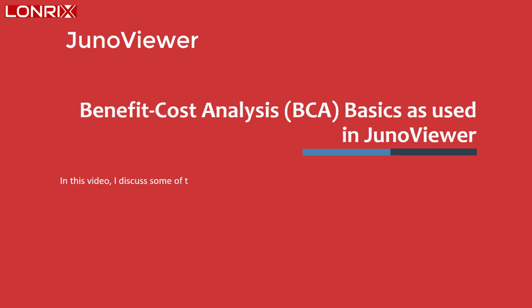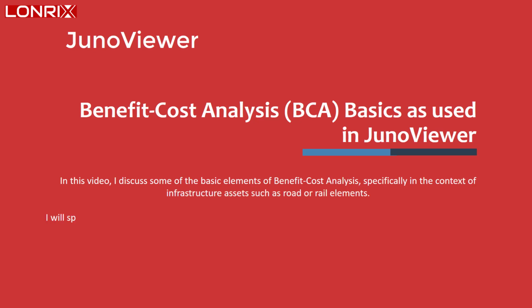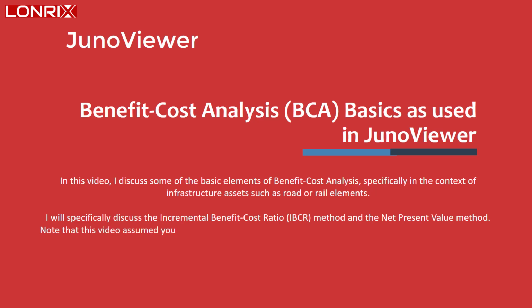In this video, I will discuss some of the basic elements of benefit cost analysis, specifically in the context of infrastructure assets such as road or rail elements. I will specifically discuss the incremental benefit cost ratio method and the net present value method.